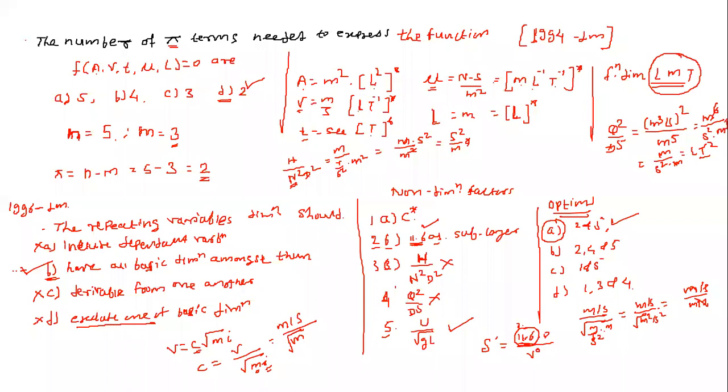Another one is related to Rayleigh's method. They had given us the question, which was asked in 1998. The question is like this: in Rayleigh's method of dimensional analysis, the dependent variable is written as a function of exponential terms of the independent variables. That is the assertion. The reason they had given is: in Rayleigh's method, when the number of independent variables exceeds 3, the exponents of non-repeating variables are expressed as the exponents of the repeating variables.